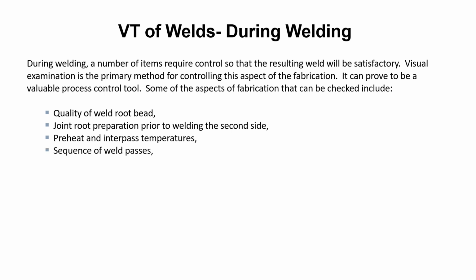Preheat and interpass temperatures are things that we need to take a look at. Did we preheat this thing? Are we keeping it warm enough while we're welding it? And that's a lot of metallurgy related stuff there. But I'm just throwing that vocabulary out there. Maybe we'll touch base on that in a different module or a different course.